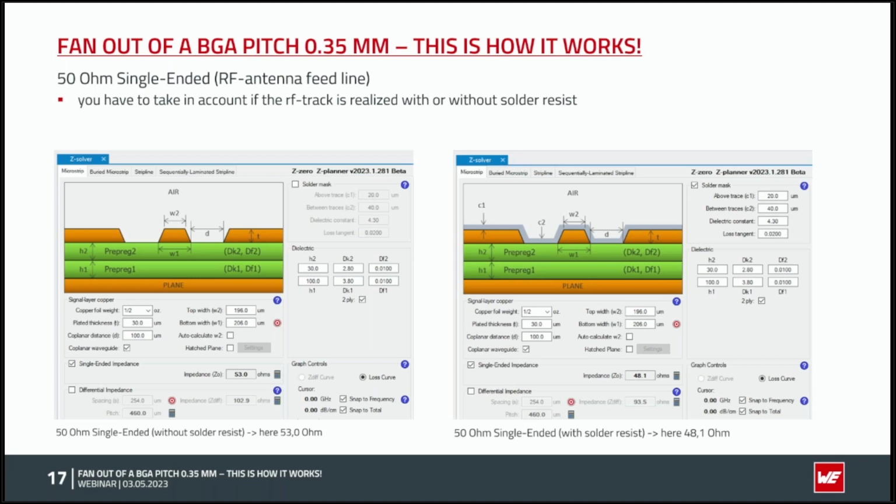So you need to know that information. You need to use that information in your stack up, in your constraint set for those certain lines, those certain tracks, so that you have the right value you need, and you have to tune it to the right value.